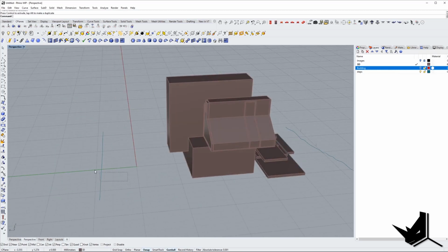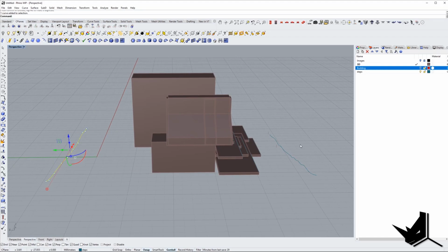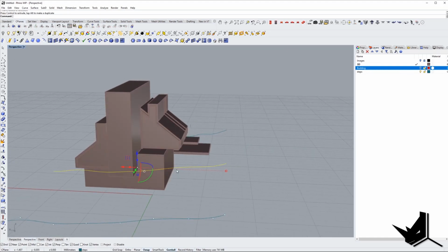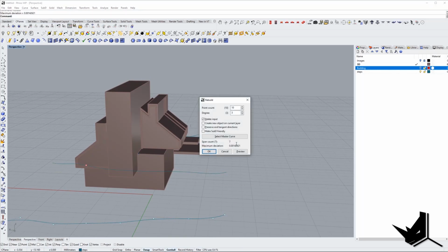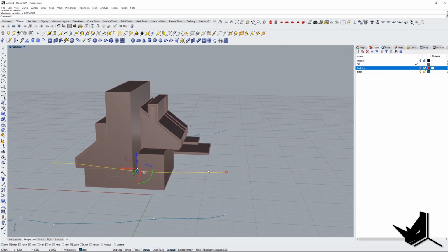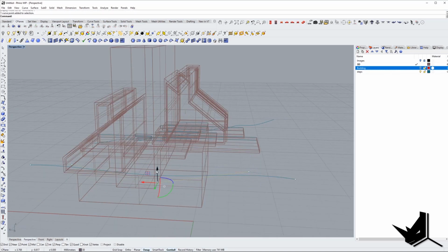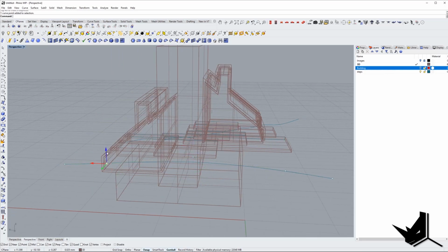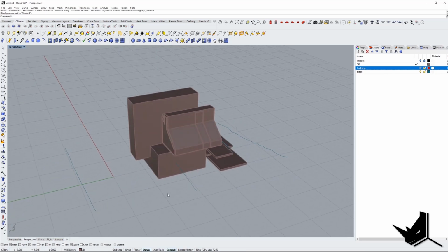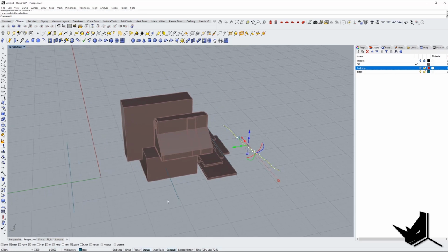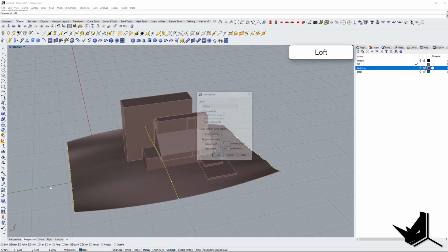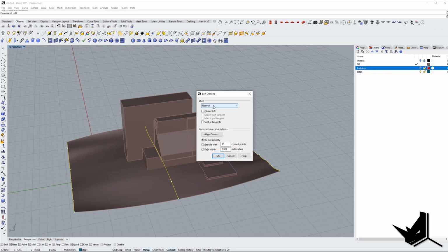And for example, what I can do, I can say I also want one line in the middle, which is maybe totally something else, but not too far away. So I'm going to say rebuild, let's say 5, and then I can use points here to actually change my curve and to have different kind of effect, maybe some hill or some valley, like this. And then the last thing, we can use loft, and we can output it as sub D.